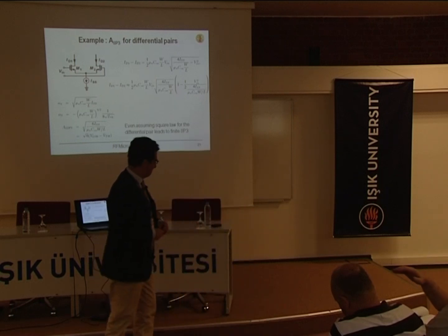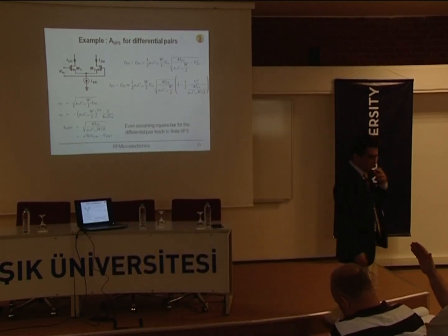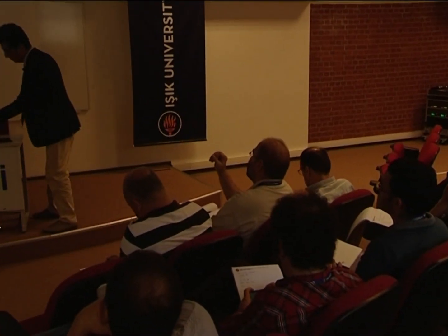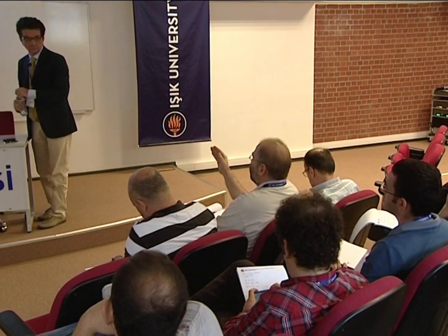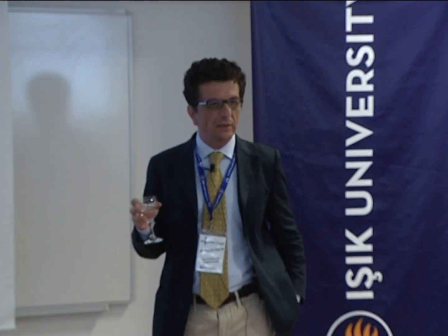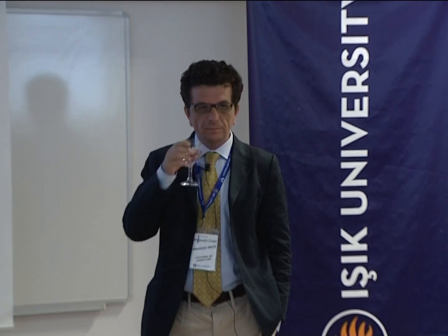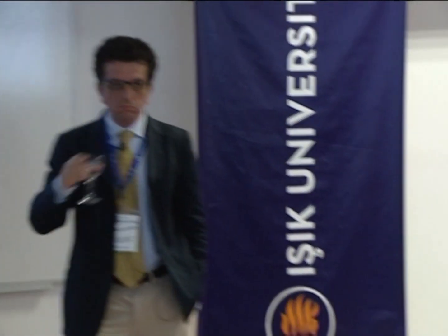Sure. For deep submicron technologies, if we increase the overdrive voltage, the transistor goes into the velocity saturation region, and as a result the square law does not hold. That's true. So if we work with deep submicron transistors, do we still have it, since it's somewhat linear? Yeah, you're right. It's a more linear relation. You tend to be more linear, but still you have third order intermodulation. So it is still true to have larger VOV for deep submicron too.